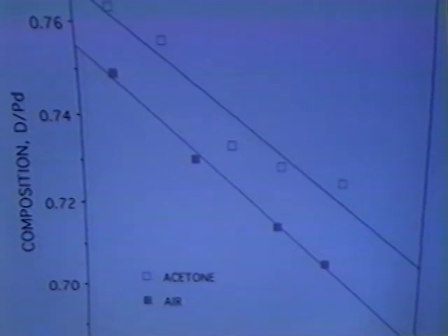Also, that curve, the one you just saw, was deloaded in the electrolytic cell. This one here was deloaded in acetone, this one was deloaded in air. They all have the same effect. They're linear and they're almost the same values for the same sample, indicating that the deloading is not occurring through the surface. That is, the surface is presented to these liquids. These liquids will change the character of the surface and therefore the deloading rate if that's where the deloading were occurring from. It's occurring from cracks inside the material which are not in contact with the liquid.